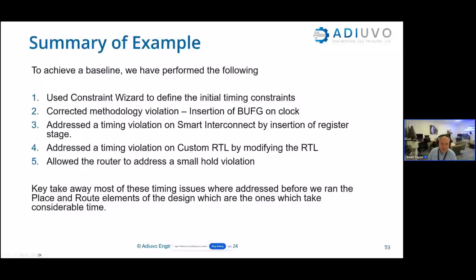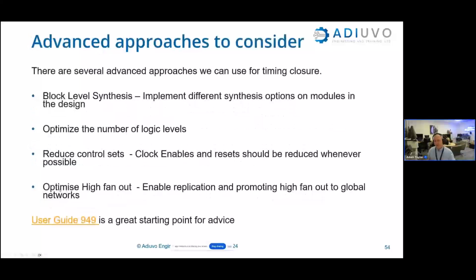I will answer that. If you want to look at some advanced concepts, and timing closure can be quite challenging, we could look at block level synthesis for different synthesis options in different modules. We can look at optimizing the levels of logic, and pulling back the levels of logic and pipelining them, as we showed in our previous webinar.